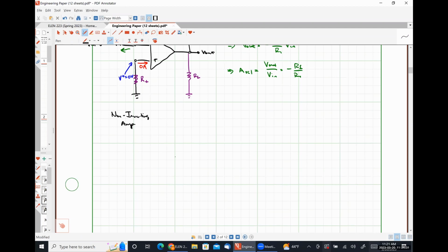It is an incredibly similar circuit. In fact, the only difference is that we are changing where we apply ground and where we apply Vn on the input side of our device. So starting with our op-amp by itself, we're going to have negative feedback. We're going to have a resistor R1 between the inverting input terminal and ground now, and we're going to apply Vn directly to the non-inverting input terminal.